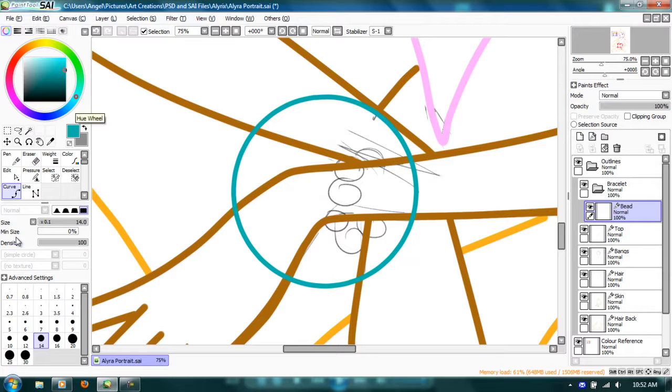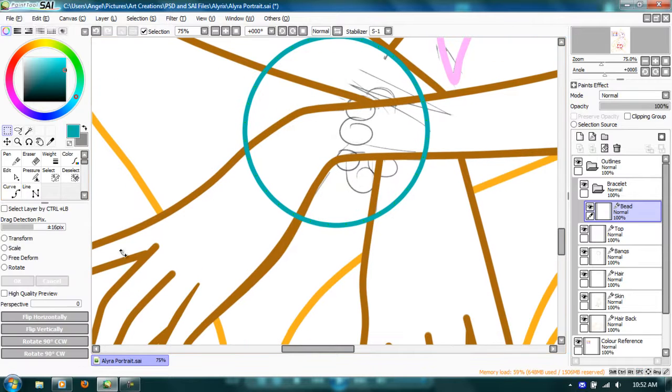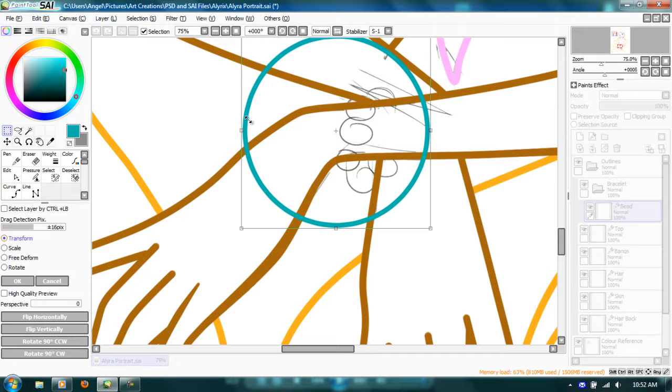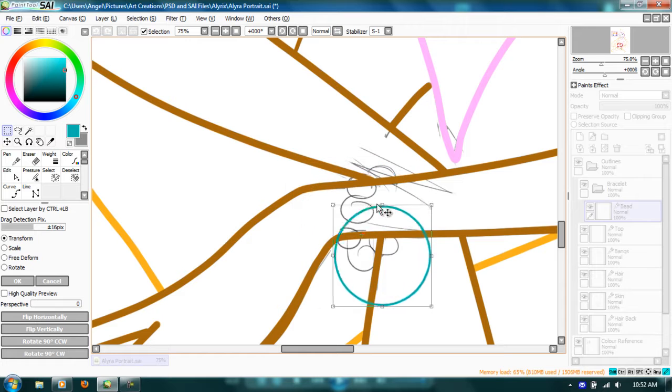To resize your circle, click the Transform tool, then choose Transform. Drag one of the corners while pressing Shift to make your circle smaller without deforming it. Press Enter once you've finished your transformation. While in transformation mode, you cannot do anything else.